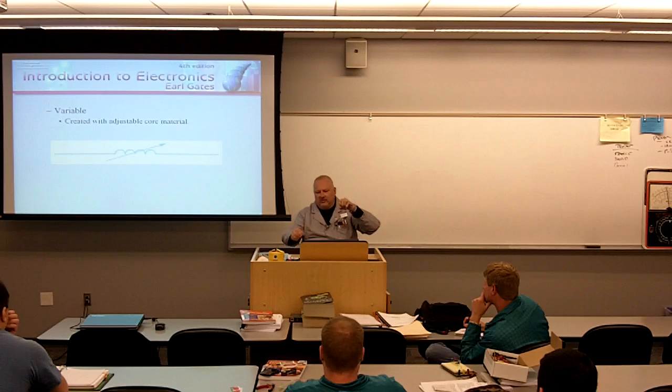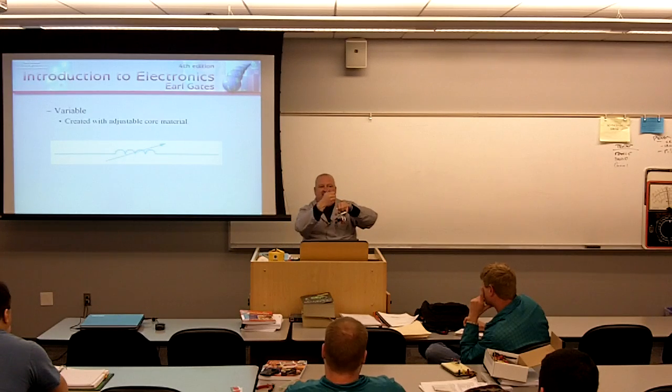And what you can actually do with it is righty-tighty, lefty-loosey, screw it in. As you screw it in, what are you doing? You're increasing the magnetic influence of the iron core. So by simply adjusting that, this is used for fine tuning in a lot of circuits that contain these. Very fine, subtle tuning.